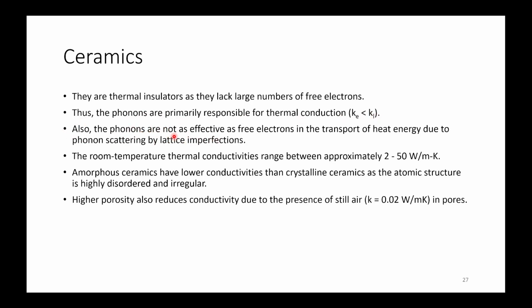Also, the phonons are not as effective as free electrons in the transport of heat energy due to phonon scattering, because there will be some lattice imperfections. So if there are, for example, some vacancies or some dislocations present, they will scatter the phonons and the heat won't be efficiently going from one part to another part.